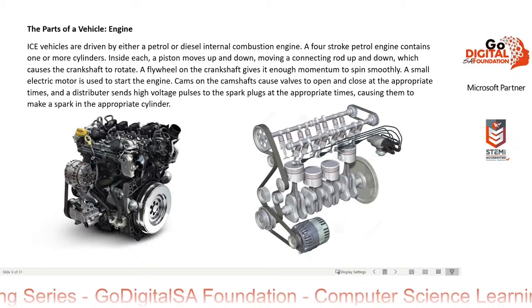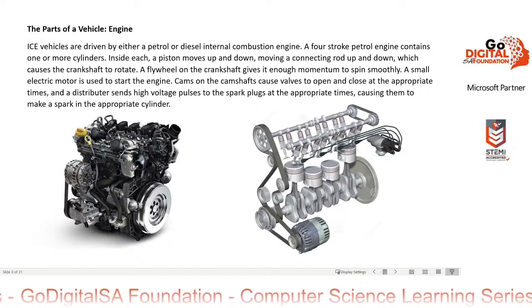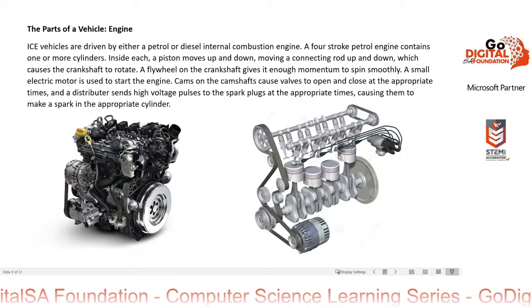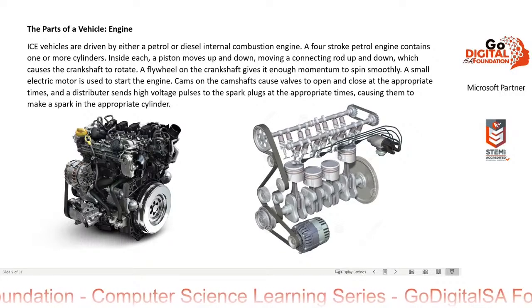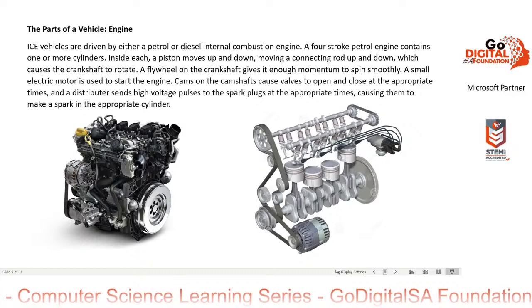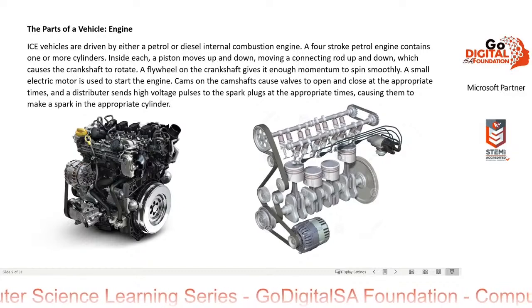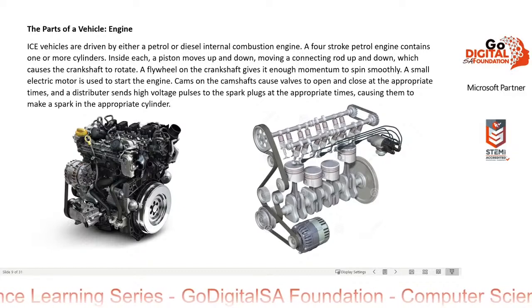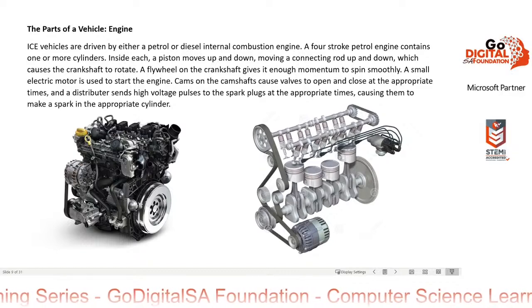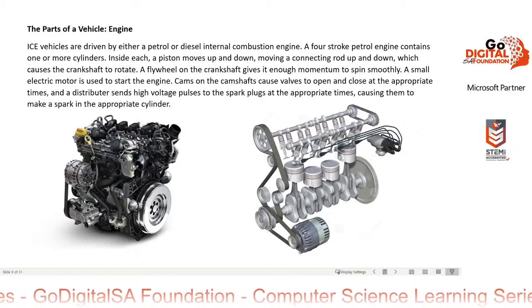A small electric motor is used to start the engine. Cams on the camshafts cause valves to open and close at the appropriate times, and a distributor sends high voltage pulses to the spark plugs at the appropriate times, causing them to make a spark in the appropriate cylinder.